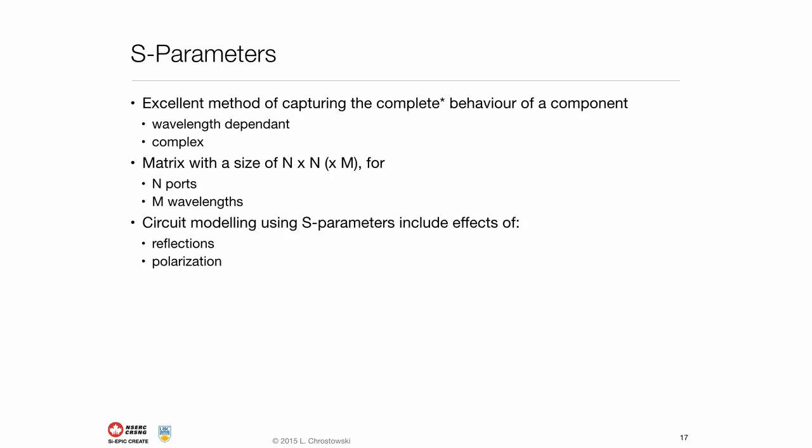Let's discuss what S parameters are. Scattering parameters, or S parameters for short, are used to describe the behavior of a linear time-invariant network. Traditionally, this concept is used to describe the response of electrical devices as a function of frequency. S parameters are particularly useful for experimental characterization of electrical devices using a vector network analyzer, or VNA.